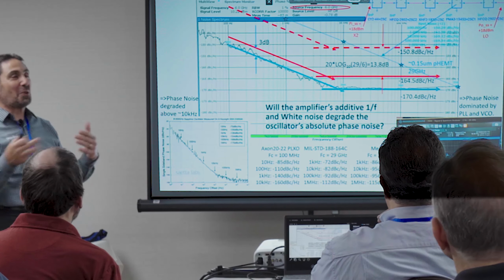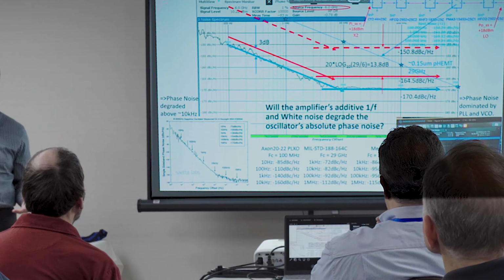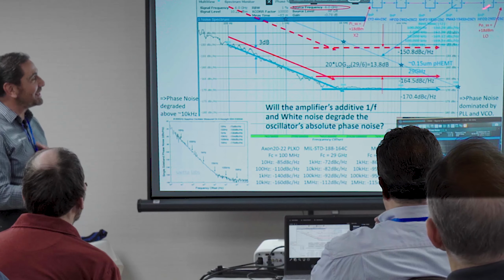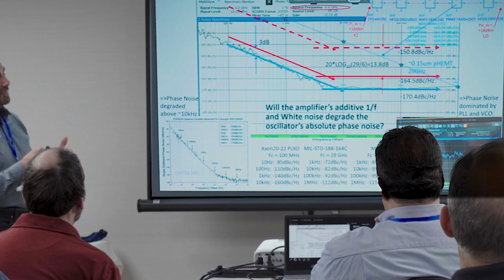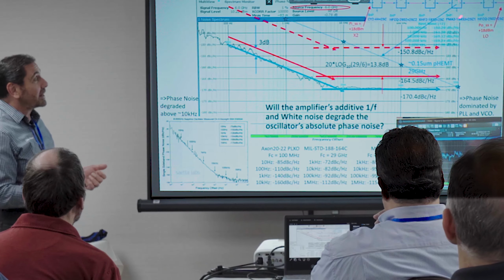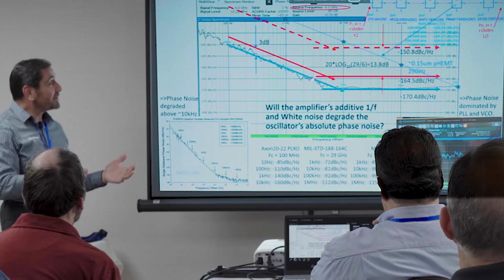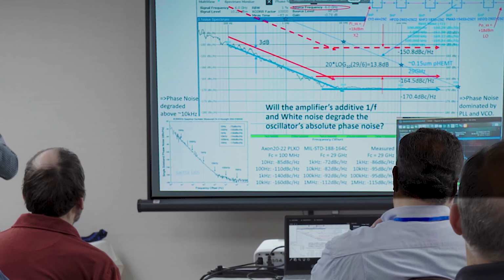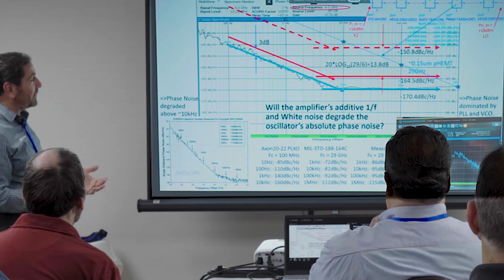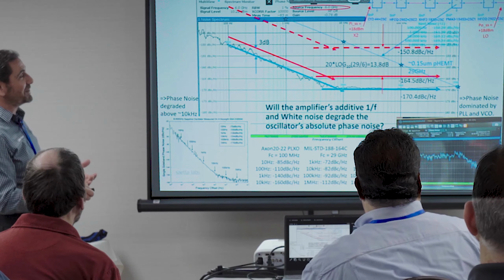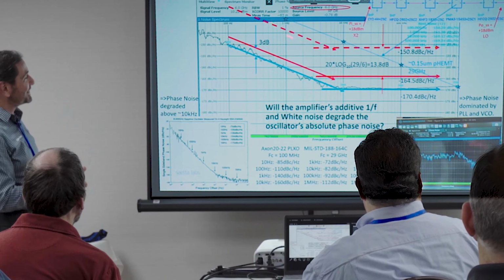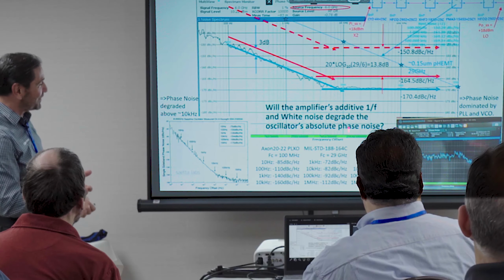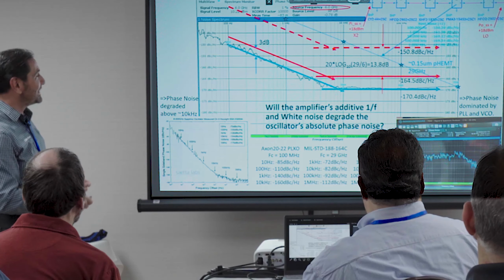That doesn't preclude you from wanting to do it correctly, but be mindful of that. So you know what? I have the room, I have the power. I'm going to balance this. Maybe I'll drop this by 3 dB. So there are things you can do, but just straight cascading, you're going to find that the last stage right before the mixer is setting my noise floor up through at least 10 kilohertz.